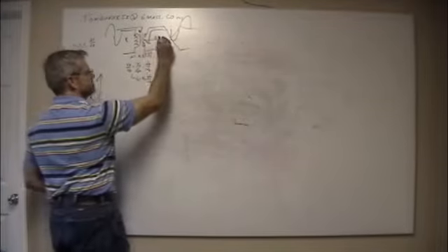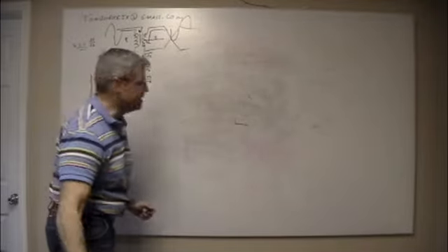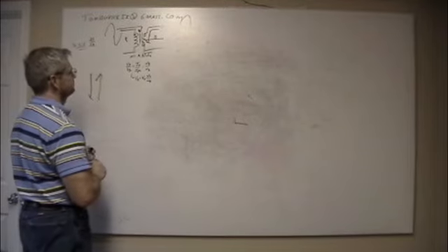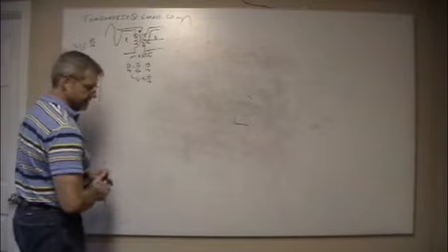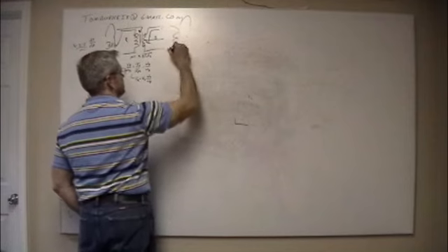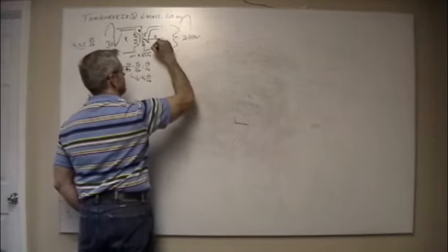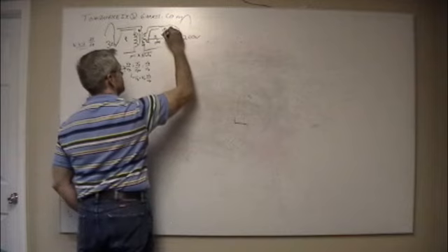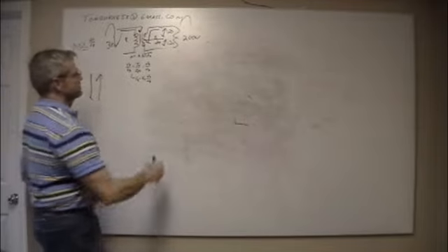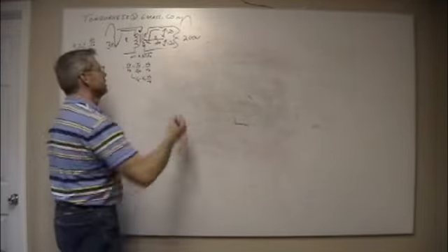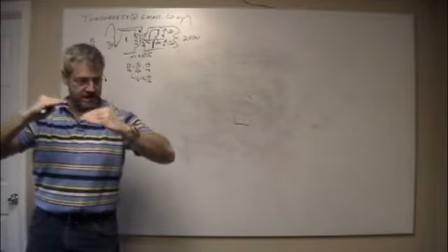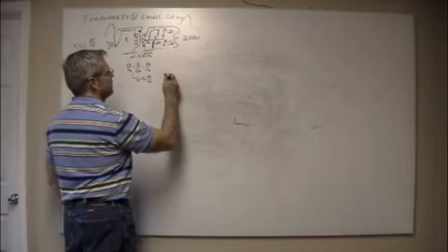And then there can be center taps, so you can do fun things. Your house, we talked about this a long time ago. Your house is fed by like 3 kV, I think, like 3,000 volts here, and this is 240 volts, but this is tied to ground, so this is 120, and this is 120. So you effectively get two 120 circuits. So if you've got a 120 breaker, it's going across this one. If you look at them, you've got breakers on the left and the right. They're opposite.